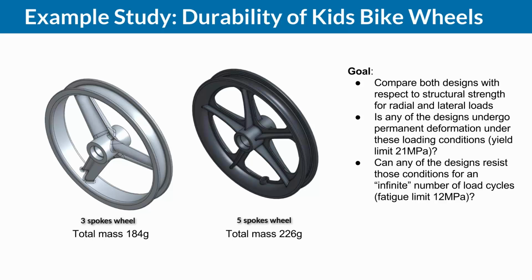The next thing is, now, I of course don't want only one rotation of the wheel. Of course, I want to have multiple thousands, millions. So how can I know if my wheel will never break due to an excessive number of load cycles? For most materials, you can have something called a fatigue limit. There's also another thing called an endurance limit. They're similar, not exactly the same.